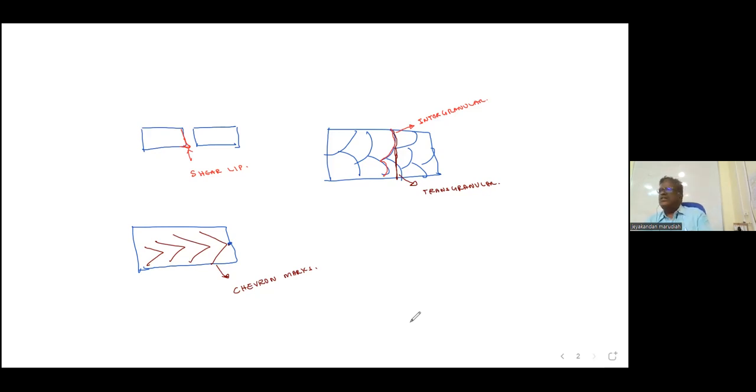Then finally, which NDT will detect brittle fracture? Another very important point: NDT cannot detect whether a vessel or tank is going to fail brittle. Only if you have a doubt, because brittle fracture starts from a surface defect, we have to check with surface NDT whether any defects are there. There only it will start. If you find any cracks developing there, then it may fail. Immediately we have to take corrective action.